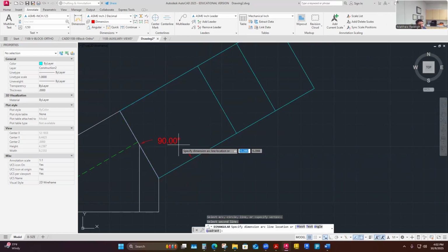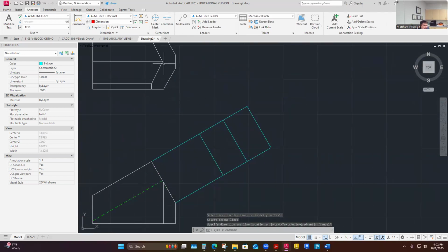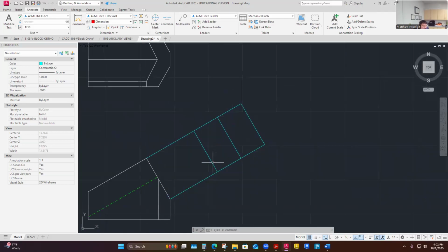I'm just careful, if I'm going to do this hack method, that I'm not going to project these pieces down. But that would be the argument for building a projection plane where you could project these down to it. Maybe I'll do that one too in the future. Really decide that the spacing here has to be so much so that this can project to it and this can project. And then we get a little bit of a better check and balance to my two views and my auxiliary view.